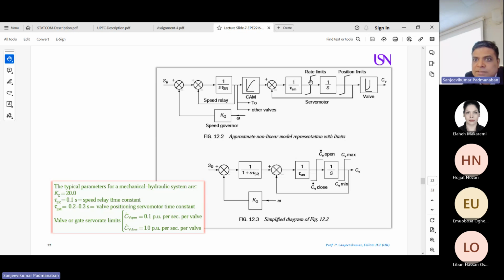Then I have a limiter. What is this limiter? This integrator is an addition over time. I'm right? You know the meaning of integration, addition with respect to time periodically. So you have limits of currents and voltage. This integrator can get saturated and can exceed the limited value. In order to fix that limit, for example, I have a machine and I know the current is 10 ampere, then I can fix the limit: maximum goes to plus 10 ampere, minimum goes to minus 10 ampere. This is the purpose of the limiter. The limiter helps you to stay within the limits and avoid saturation of your machine.